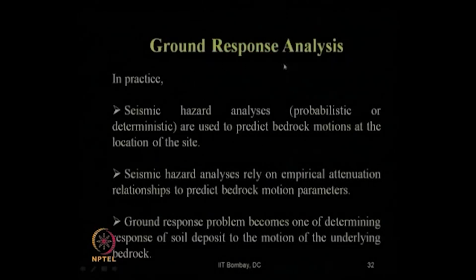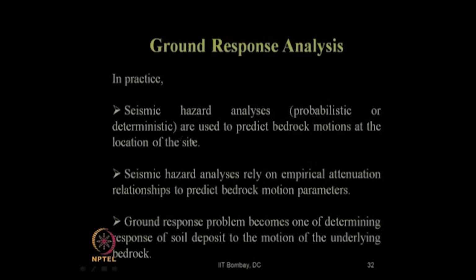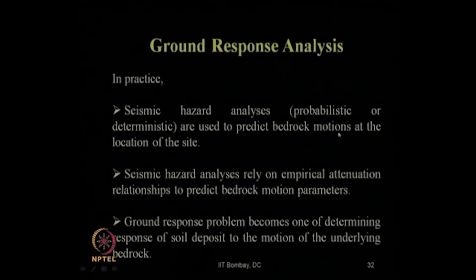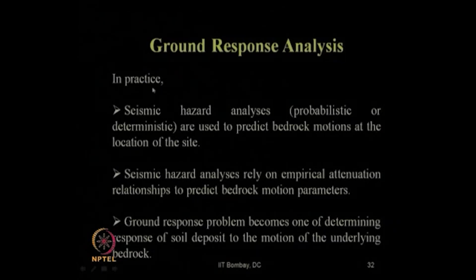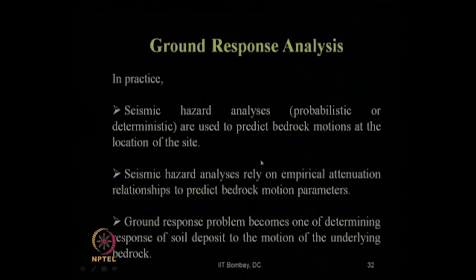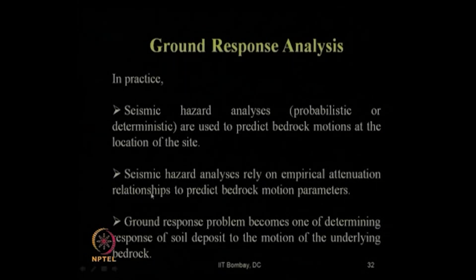So, in practice for ground response analysis, we do the seismic hazard analysis. It can be probabilistic or deterministic or a combination of both, used to predict the bedrock motions at the location of the site. That we have already discussed in detail in our previous module, right. When we do the seismic hazard analysis, it relies on empirical attenuation relations, which we have also seen, because all the attenuation relationships are empirical, based on past earthquake data.